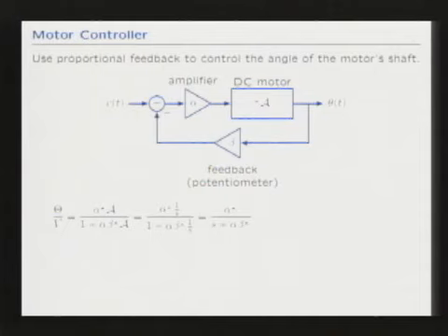I've taken off the little stop so that it spins around and doesn't hit the stop, otherwise it would be kind of bad for the first part of the demo. So it's a surgically altered potentiometer that spins around forever. But over most of the range, it's reporting angle. That's the way I get this feedback loop in.